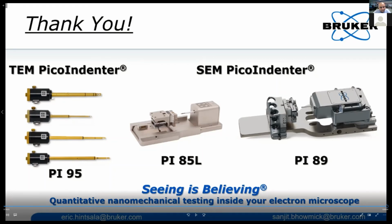Then another question that we have is, suppose we have done room temperature nanoindentation on one sample, can we use the same sample for high temperature nanoindentation? Well, yeah, if you're not subjecting it to a higher temperature, because in nanoindentation you can do plenty of indents on the sample. So as long as you don't have any history, if you're starting from room temperature to a higher temperature, it should not be a problem.